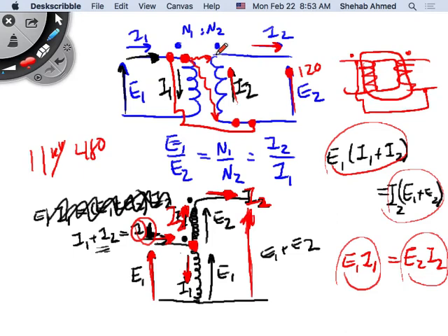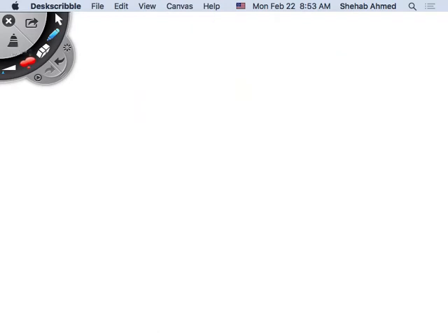In Qatar, we have a 220 kilovolt network and a 400 kilovolt high voltage network, right? You're not coming close to these anyway. And you have to transfer power between the two networks, right? Remember, we generate, then we step up, to whatever, say 20 kilovolts up to 400 kilovolts, if you're connecting the transformer directly to the 400 kilovolt network.